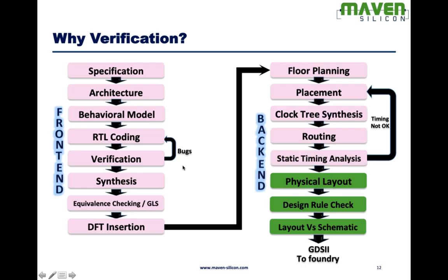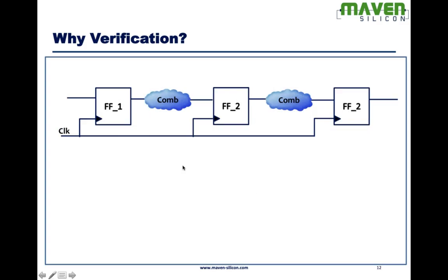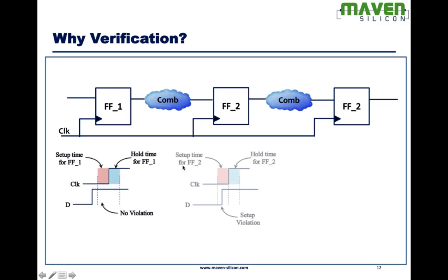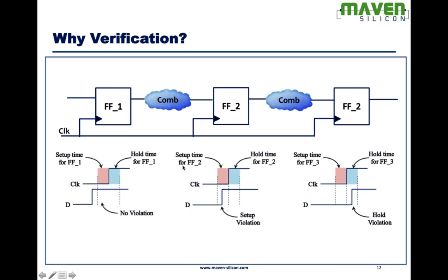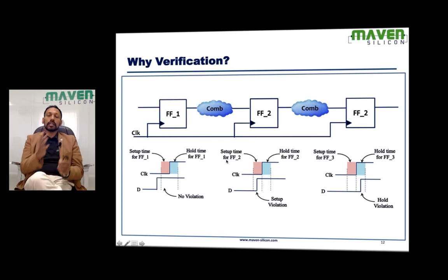That's where we apply the static timing analysis methodology. For every flip-flop, we need to follow setup time and hold time. Are there any setup time violations? Are there any hold time violations? If there is any violation with respect to setup time and hold time, eventually the design will get into a metastable state. So in order to avoid the metastable state, we need to take care of setup time and hold time. And we use static timing analysis to verify such timing violations.